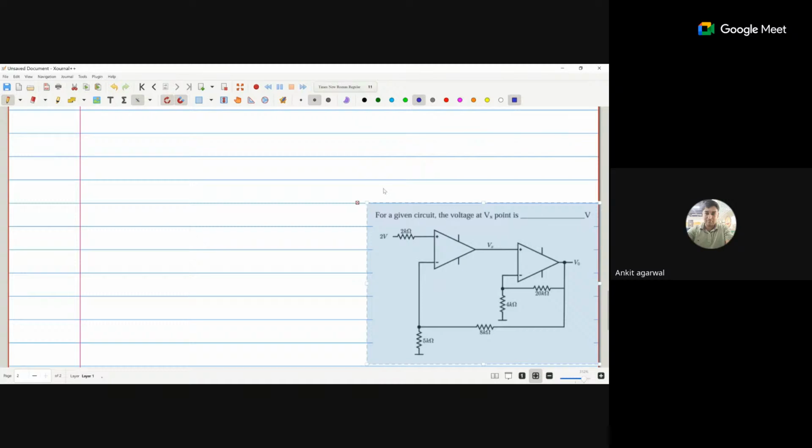First of all, I see the feedback. So what can I do? I just break the loop and increase the voltage. So the voltage will go in this direction. For this operational amplifier, for example, the voltage increases, multiplied with a negative, that means the voltage decreases, in the downward direction. So the second amplifier is an operational amplifier in negative feedback.